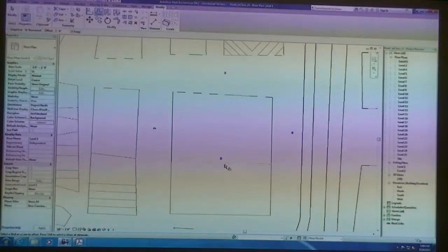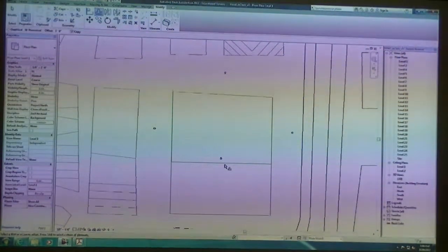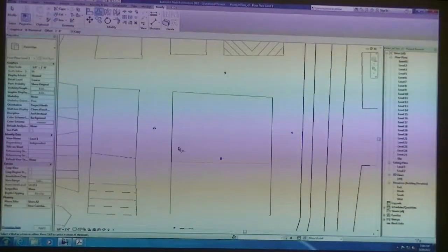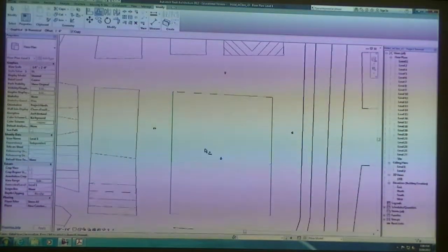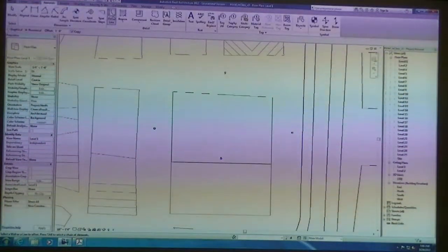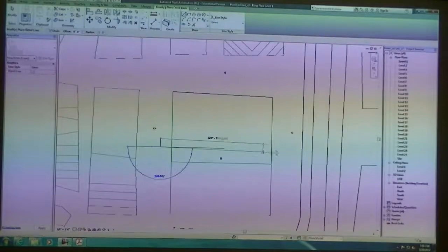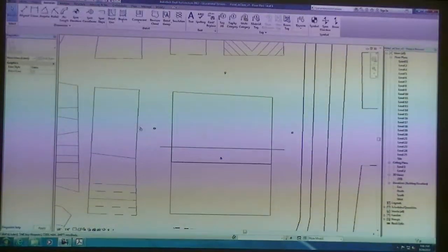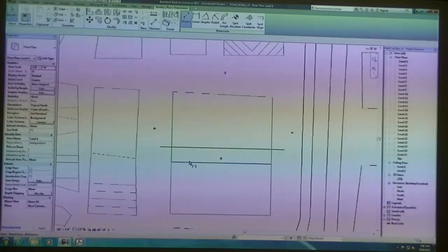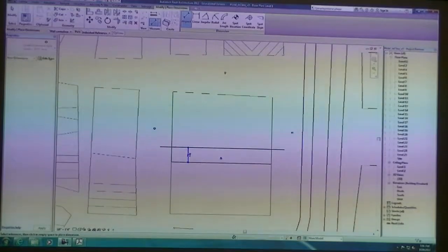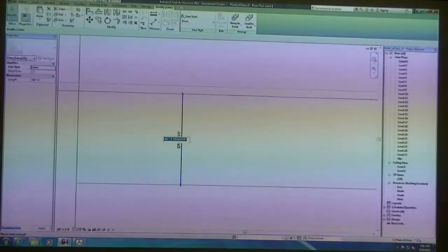And in the building code, the International Building Code, when you start to build on a site, you have to assume a property line. When we have a property line that's right here, that's essentially the face of this building, we are actually going to assume that the property line by code is going to be 30 feet away from this building face. So I'm going to draw a line, just strike a dimension, and then select that line, and then type in 30 feet.